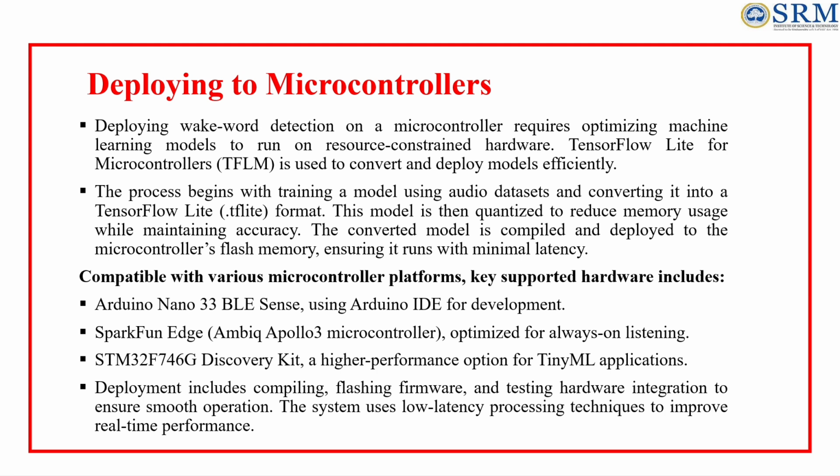Finally, after the deployment, we test the system with real audio. We check whether it detects the wake word correctly, confirm the latency is low, and make sure it operates smoothly without draining too much power.